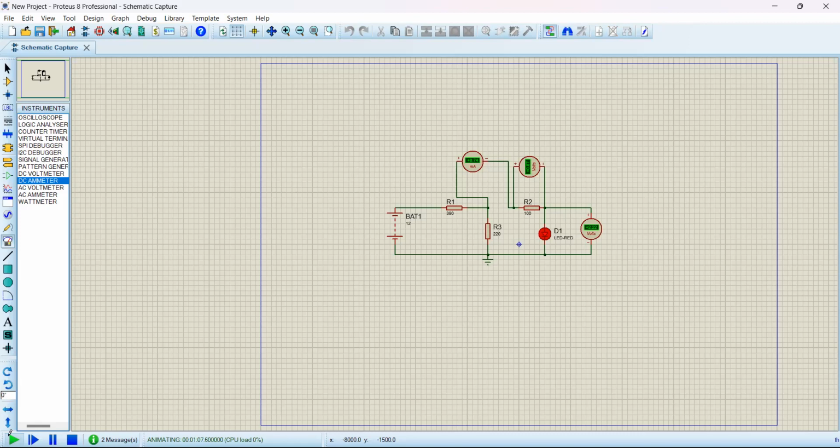You'll only see the component being damaged when you connect it in real life, because Proteus won't tell you the voltage is too much for your component. So you need to use the engineering mindset. You need to know the maximum voltages of your component before you supply. Components have a minimum voltage and a maximum voltage. Once you exceed the voltage, you might damage your component. Therefore, that's how we use Proteus and how we connect.